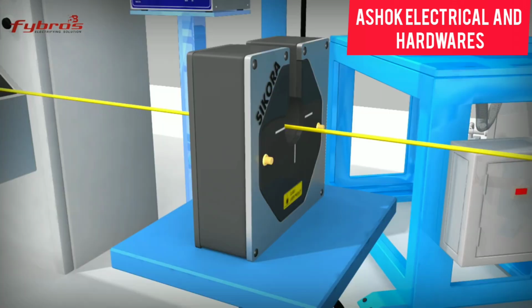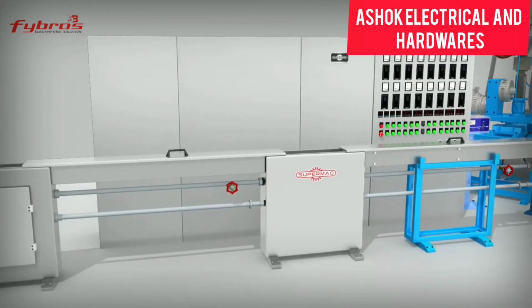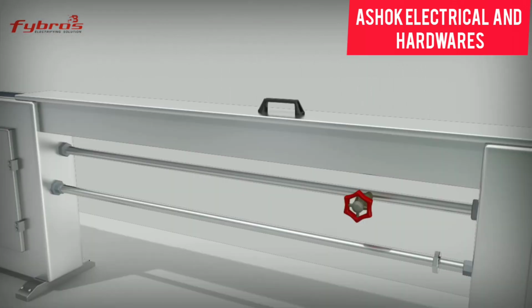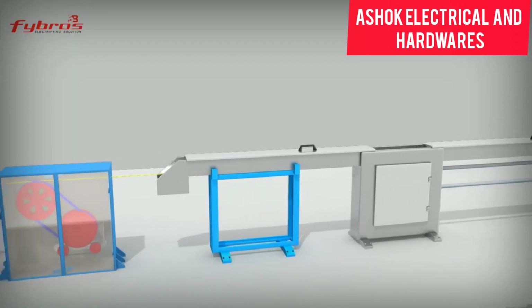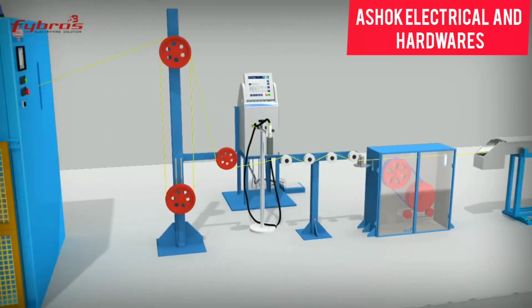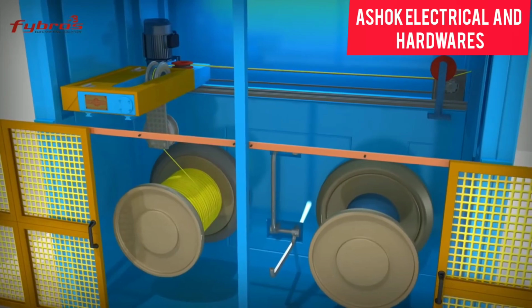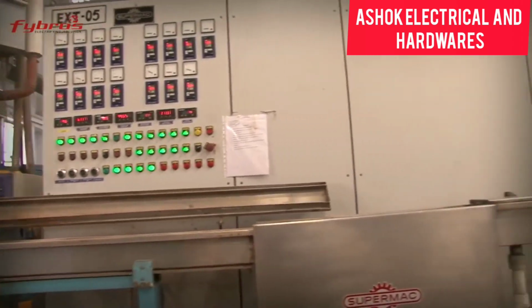After this, to maintain the uniform thickness, the wires are processed through the online diameter controller Sikora device. Then the wire undergoes a multi-pass cooling process before entering the air wiper and capstan unit. We use a non-contact inkjet printer, which helps us in continuous printing with sequential markings throughout the cable length. It helps to have a correct and complete length of every drum and coil. Finally, the bobbins are wound at a speed of 600 meters per minute with an automatic dual take-up, which shifts from one bobbin to another without a break, resulting in high productivity.